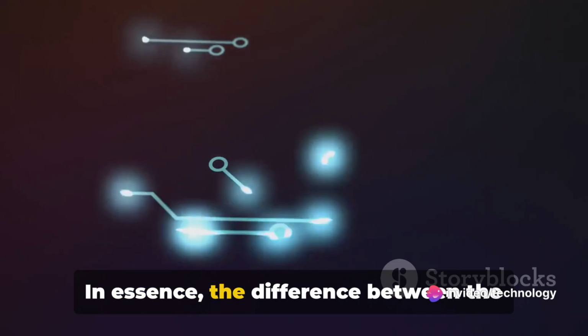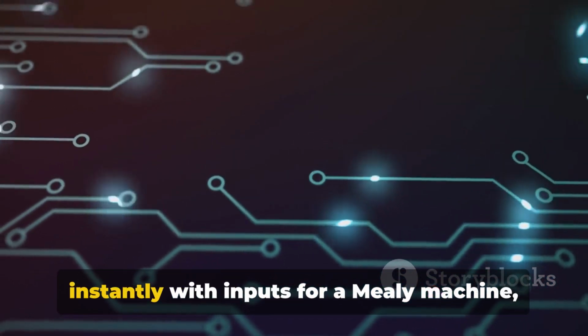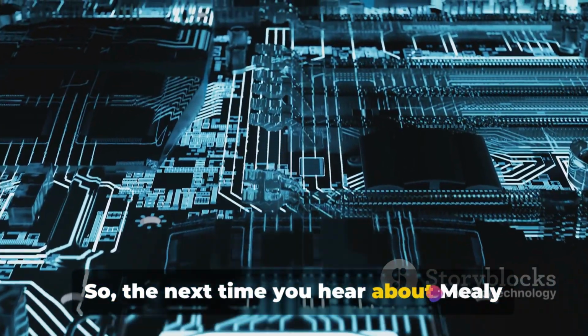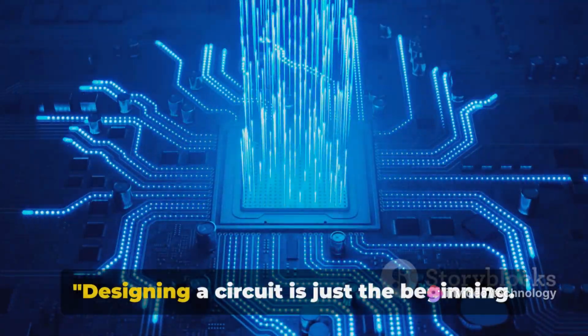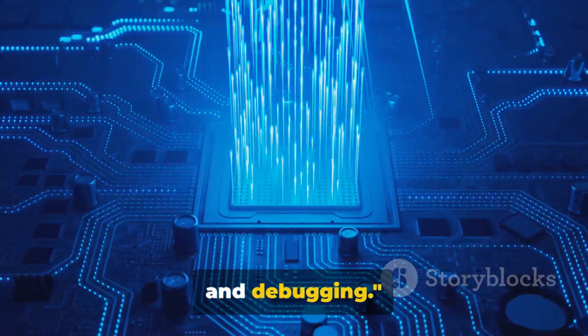In essence, the difference between the two boils down to when the output changes. Instantly with inputs for a Mealy machine, or only at clock edges for a Moore machine. So the next time you hear about Mealy and Moore, remember they are not machines, but critical concepts in sequential logic design. Designing a circuit is just the beginning. The real challenge lies in its testing and debugging.